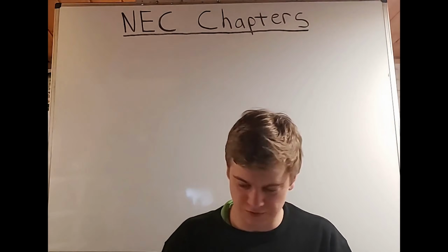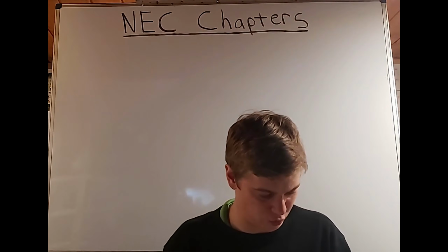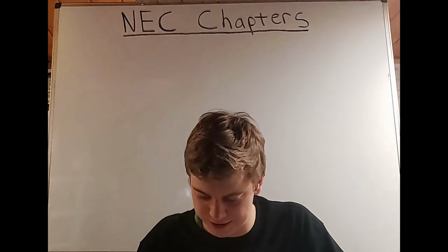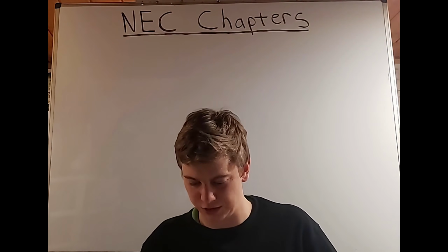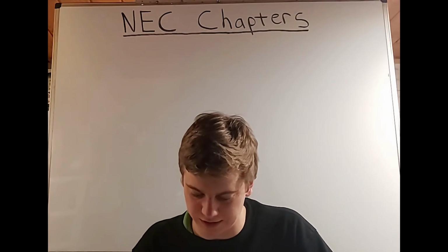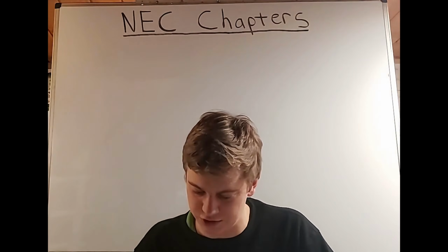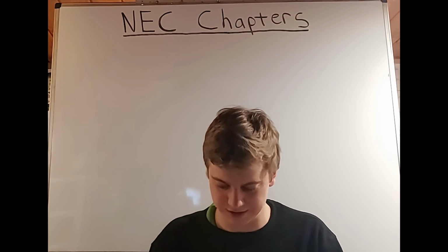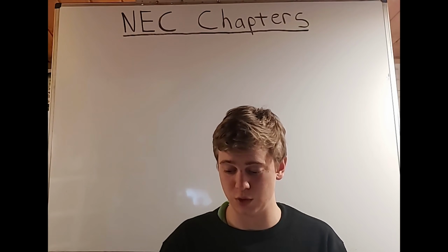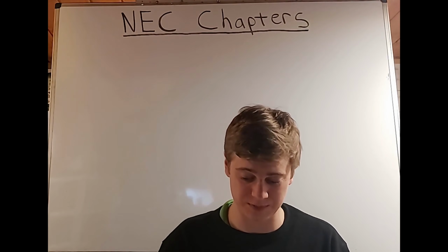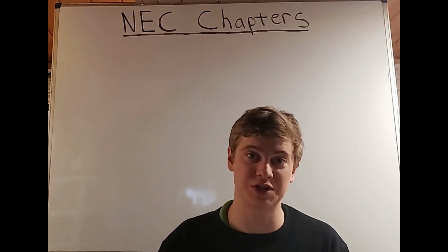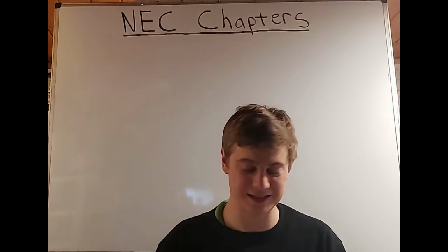Okay, we're going to flip forward to Article 110, requirements for electrical installations. We're going to look at Article 110.13, mounting and cooling equipment. We see it talks about mounting electrical equipment, and it says that it shall be firmly secured to the surface on which it is mounted. And then it further mentions that wooden plugs driven into holes in masonry, concrete, plaster, or similar materials shall not be used. Okay, so I've seen that question before.